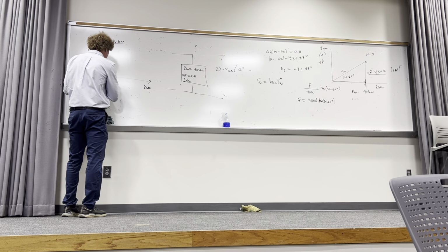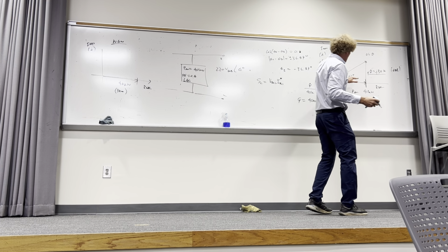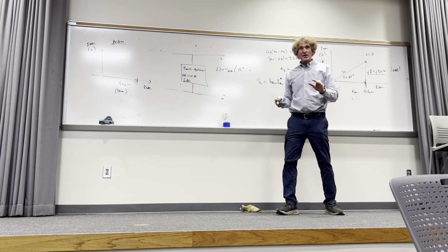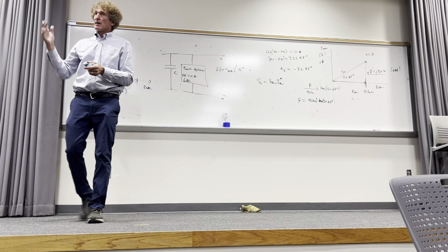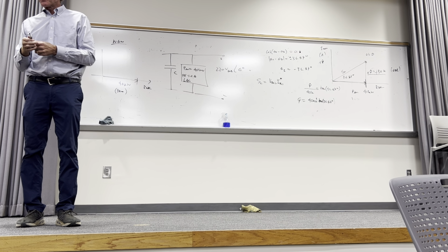The power factor was 0.8, or the cosine of this angle was 0.8, right? Now the cosine of the new power factor, when you add this capacitor, that I'm about to show you here, when I add this capacitor, now the power factor becomes 0.9. That's stated explicitly in the problem. Y'all follow me?